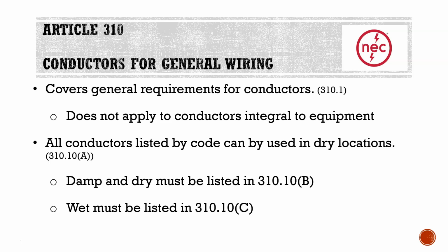So any conductor, once again, can be used in a dry location, but if we're going to be using them in a damp or a wet location, we need to verify in 310.10b and 310.10c whether we can use that type of conductor in that type of area.